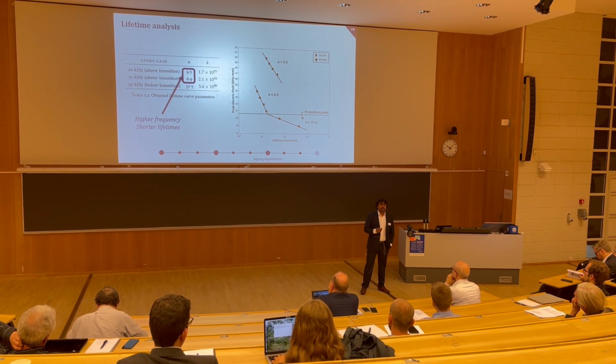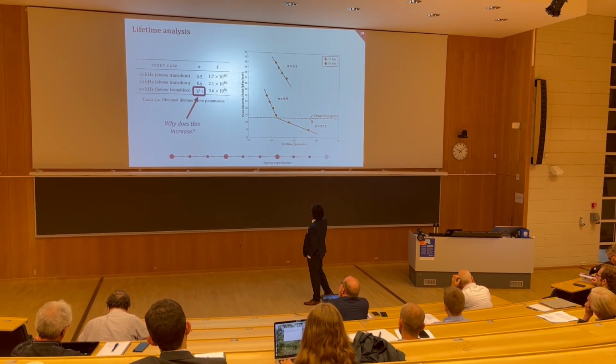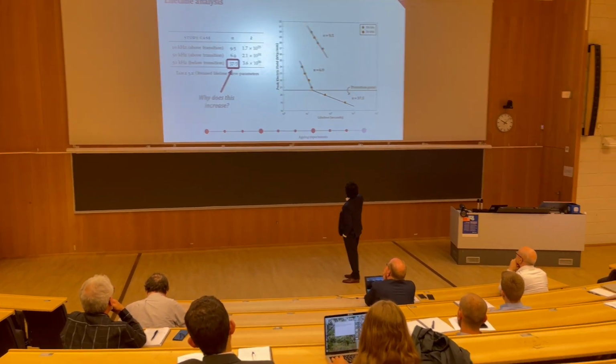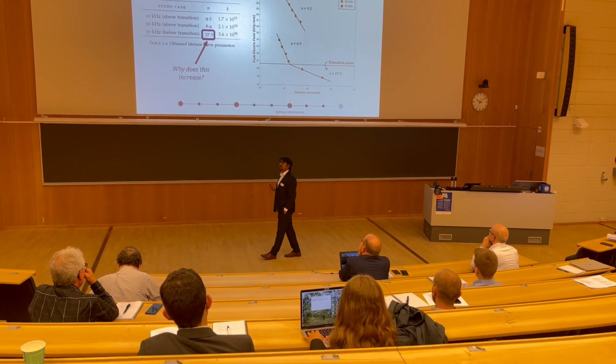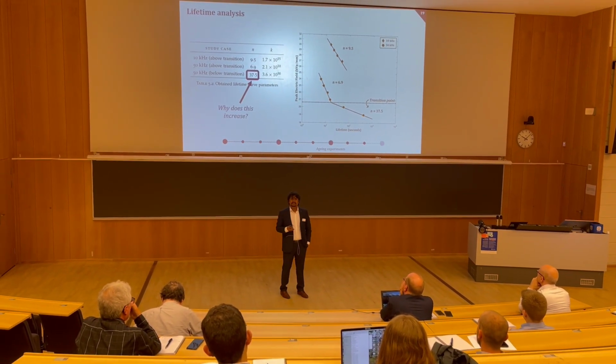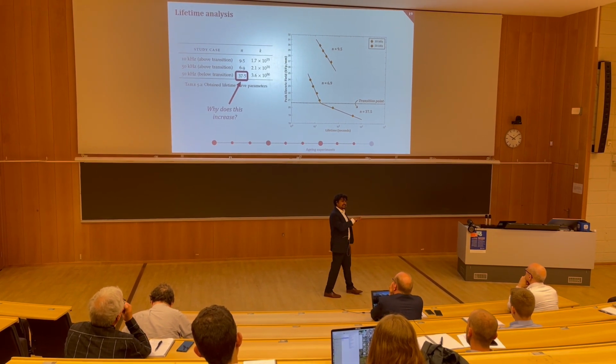The second thing which was interesting that we saw was this transition point. You see here in the 50 kilohertz line. Below a certain value of field, around 20.5, the slope of the Weibull lifetime plot drastically reduced.